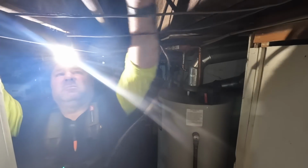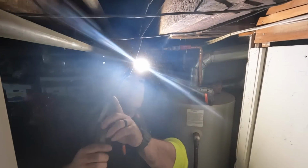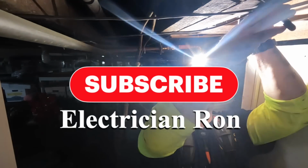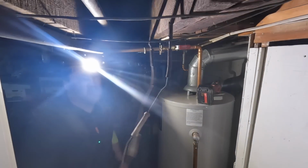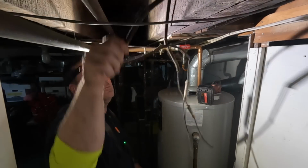So you can see the wire flapping in the breeze right there, the Romex wire behind me. I think it's there someplace. Anyway, that's what I'm doing. I'm making a path to bring that wiring from the new receptacle, where I'll also put in a pull chain light over there by the boiler later on, so that they have a service light as required by the code. And then we'll put in a pull chain with a receptacle so they have a place to plug in. And I believe this whole circuit's going to be arc fault GFCI protected as well, as required by the code.